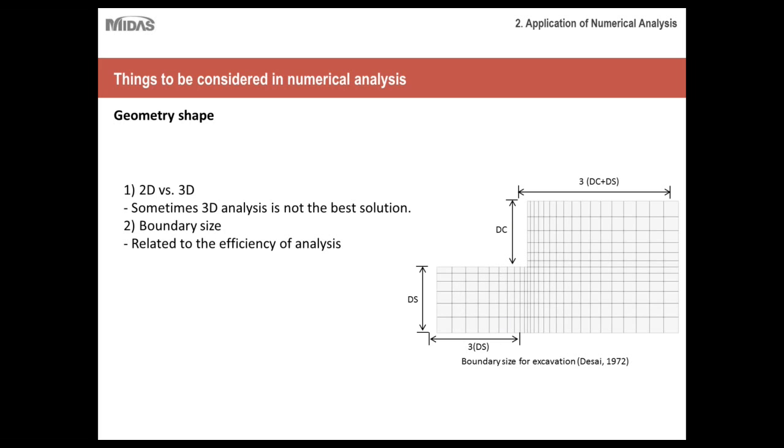We'll discuss how to select your boundaries a little more later on, but just keep in mind that you want to make your boundaries to a point where you include all of the area around the area of interest, but you also wouldn't want to make it so large that your analysis would run longer than it should. And we'll give very detailed instruction on how to select your boundary conditions when you're running your numerical analysis.